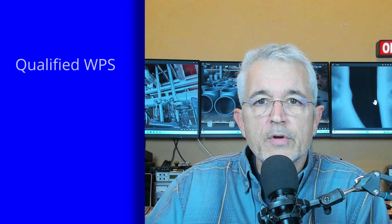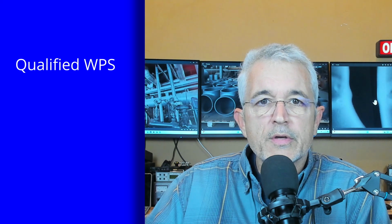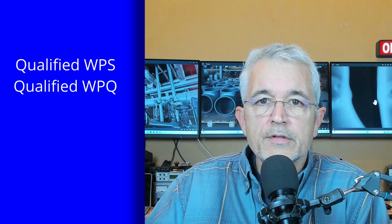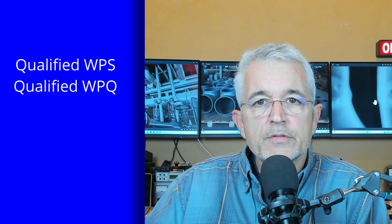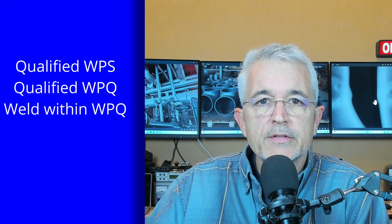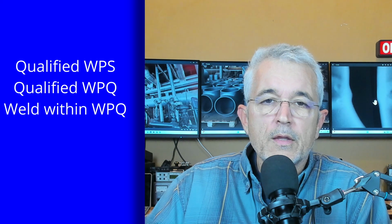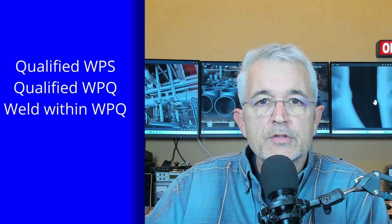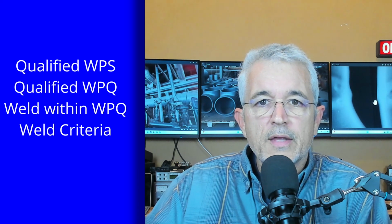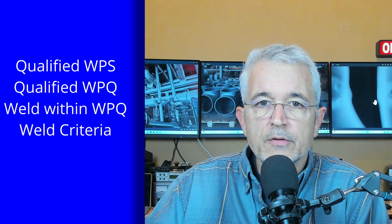So, a general recap for anyone who is not a welder. First of all, a welder needs a qualified welding procedure, and it must be according to the design code. A welder must be qualified to weld all items according to the design code. Qualified welders must weld within their qualification limitations, such as pipe size, base metal, filler metal, direction of travel, position of weld. Also, qualified welders must know the acceptance criteria for the weld. When a welder applies their stencil to the weld, they are indicating both the weld and the welder meets the acceptance criteria per the design code.